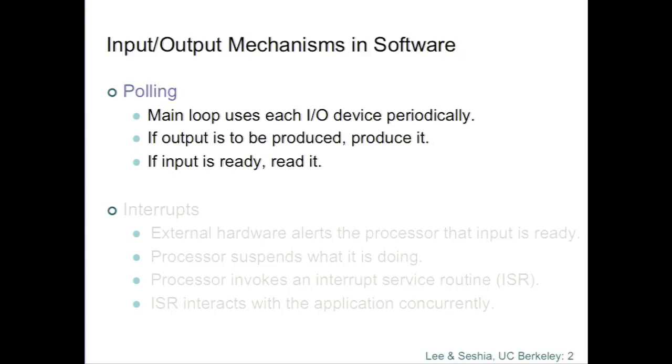One of the suggested projects for people involves controlling individually addressable LEDs on LED strips or LED panels. And these devices, the way they're designed today, in order to actually control these LEDs, you need very precise control over the timing of the software. So part of the design exercise is how do you talk to the physical device where the behavior of the physical device is very timing sensitive, and you're using a programming language that doesn't give you any control over timing. So there's a mismatch there, and you need to understand the underlying mechanisms quite a lot.